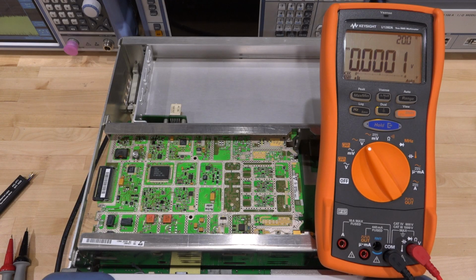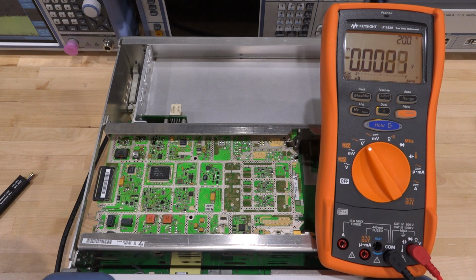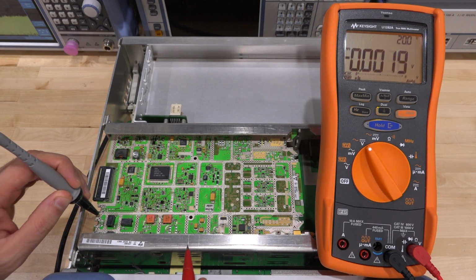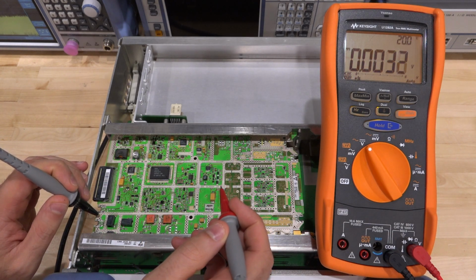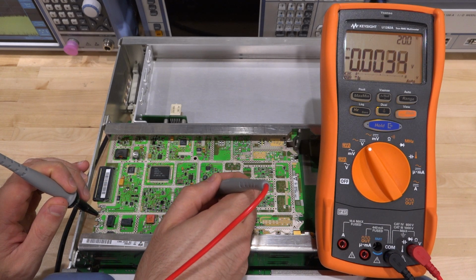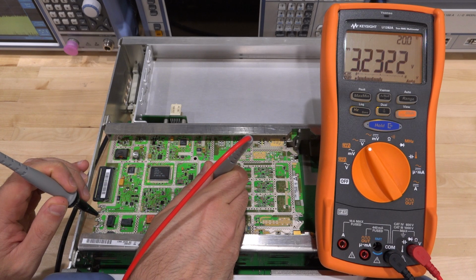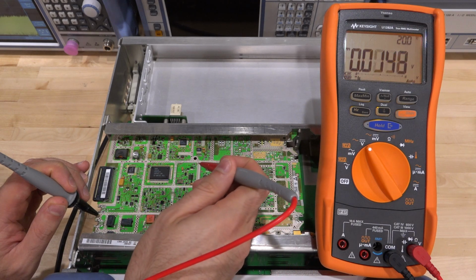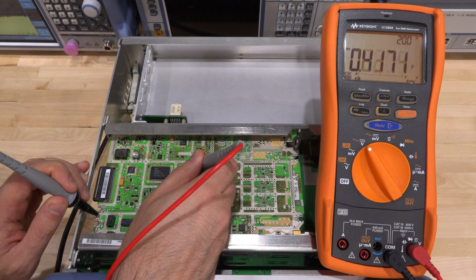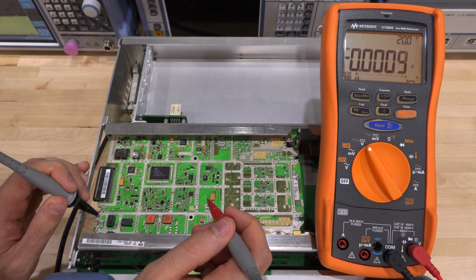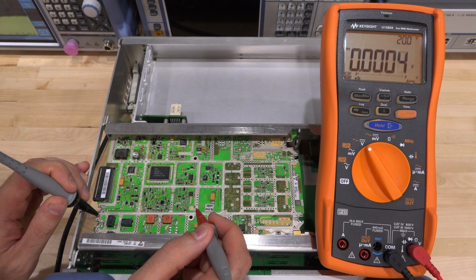Before we do any RF measurements, we can just do a couple of quick power supply measurements to make sure none of those are missing on some of these critical PLL components. So I'm going to ground over here. Let's measure the power supply of our VCO, which if I'm not mistaken is here. There you go, 3.3 volts. That looks good. So our VCO definitely has power. Check the power supply of our TCXO, 1.5 volt. Looks good. Those are the main two things I wanted to check. Those are the main ones I'm going to measure right from the beginning.